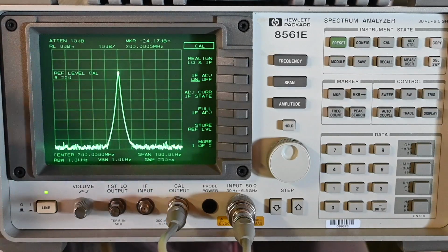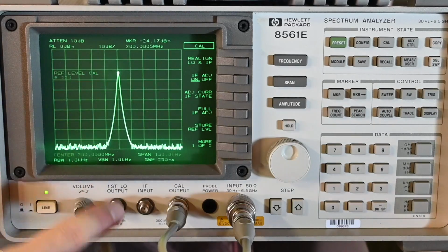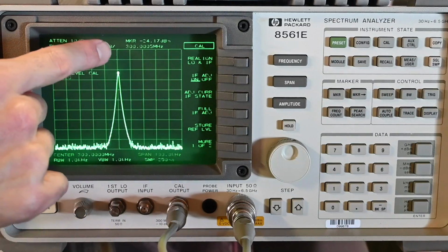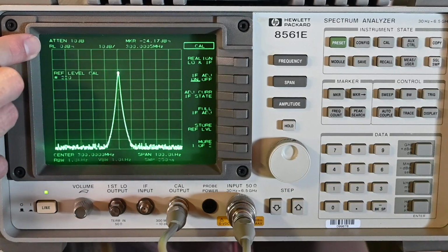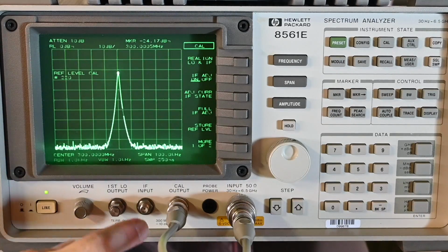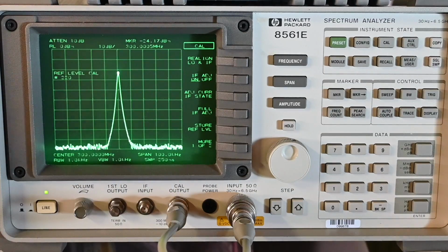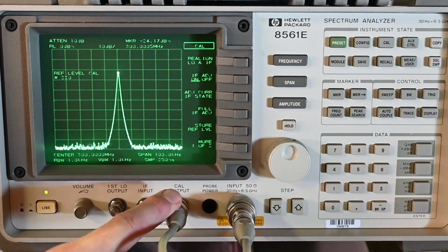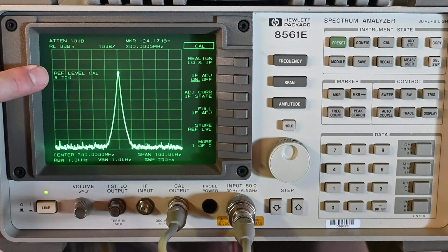But what that number adjusts when you change that is this point where the peak of the signal touches the reference line. If this was working correctly, it's basically a fine adjust, so that you can get this peak just to touch that reference line, and you would actually have it set so that the reference line is minus 10 dBm, and then when this is an output of minus 10 dBm and everything touches, you know, it's calibrated. So it's a real easy calibration, and of course it's all relying on this signal being accurate, and it was at one point. So this has always been at 220, and in the past 220 did touch a minus